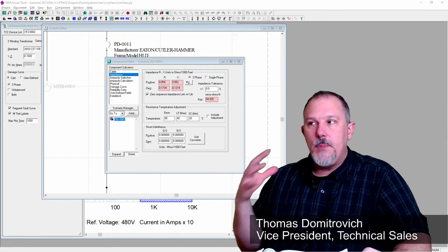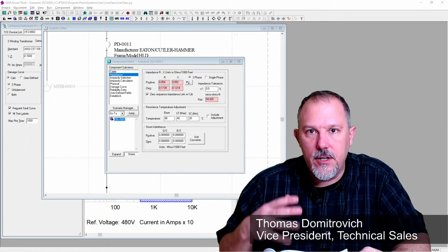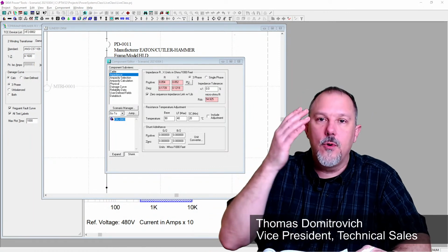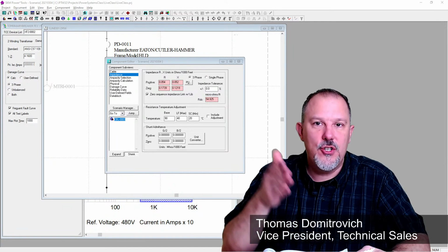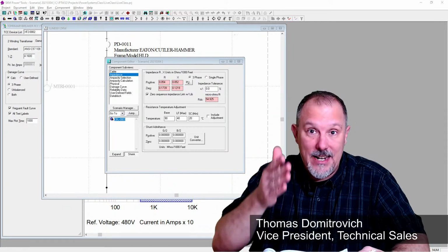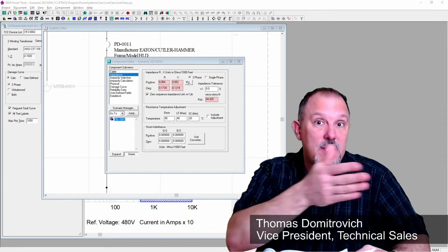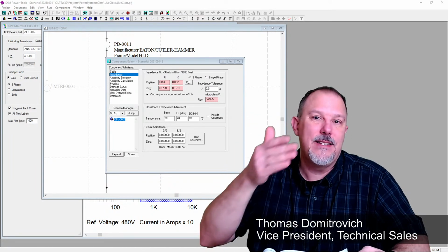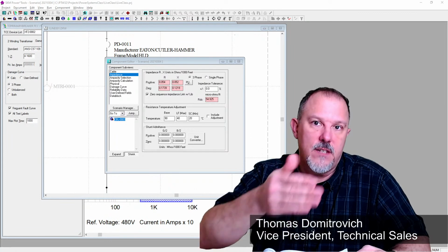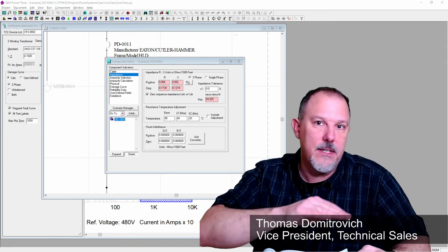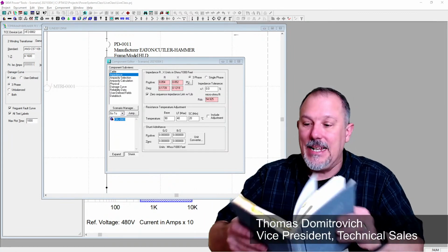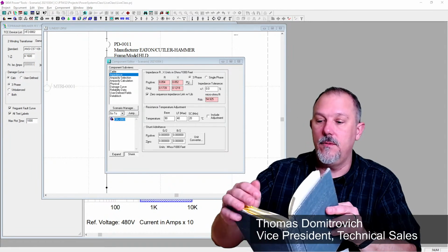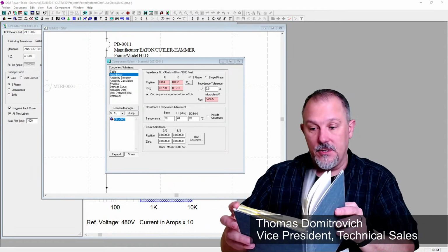So when you're doing your impedance diagram for calculating ground fault currents, your positive sequence is the impedance of the transformer. Your negative sequence impedance is the same as the positive sequence for that transformer, and your zero sequence is the same as well. So that doesn't change. But in here, they also get into the discussion of conductors.